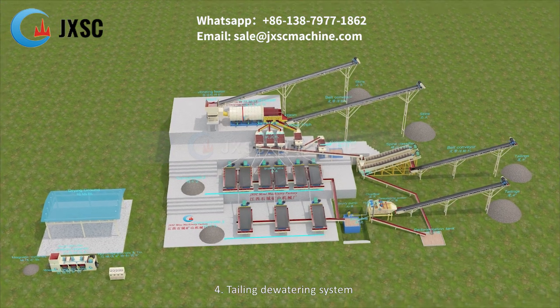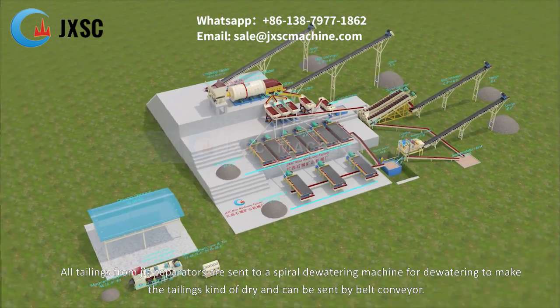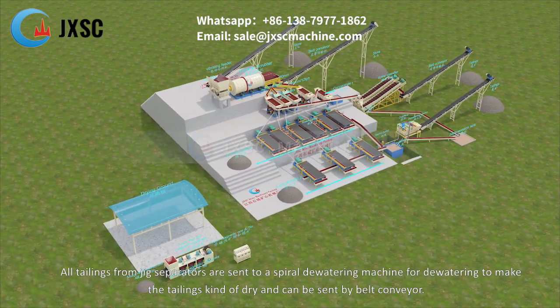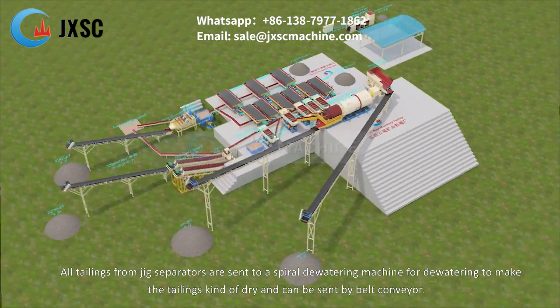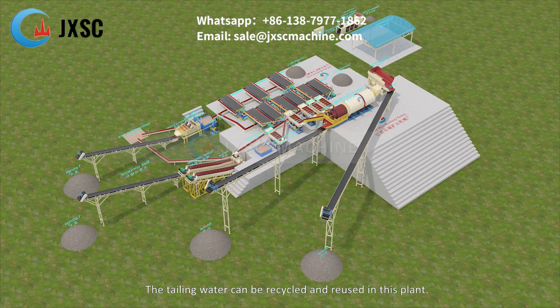4. Tailing dewatering system. All tailings from jig separators are sent to a spiral dewatering machine for dewatering to make the tailings kind of dry and able to be sent by belt conveyor. The tailing water can be recycled and reused in this plant.